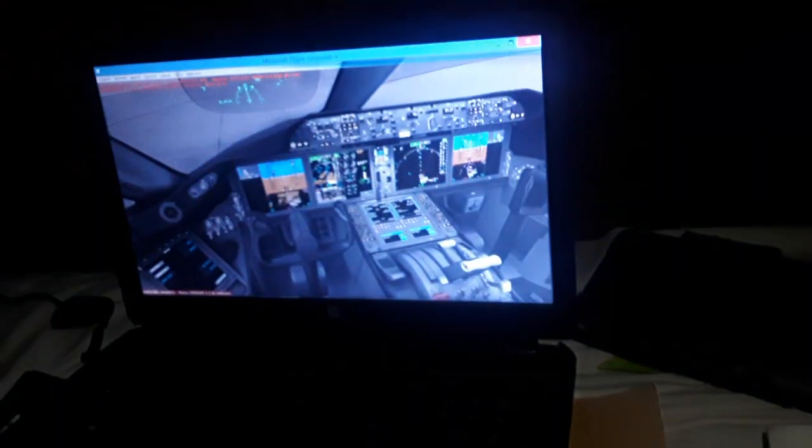So we'll input all the data we need for that. We have also the terrain map with the elevation of the terrain around you, so you can look if you have a mountain close to you with the red, green, and yellow, and the display of the airport names. We have also the vertical deviation display that displays the vertical flight path of the aircraft that we have created using the flight management computer. This control display unit that I'm gonna show you in a while.